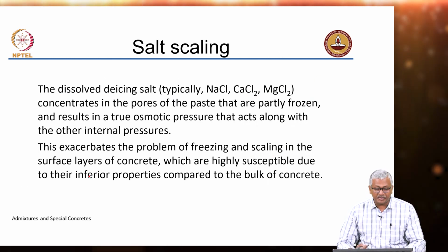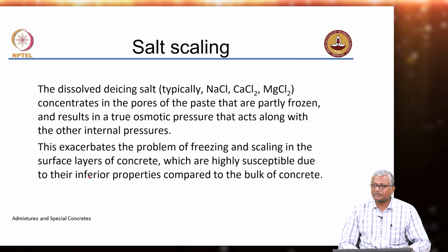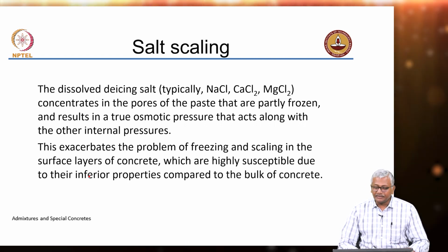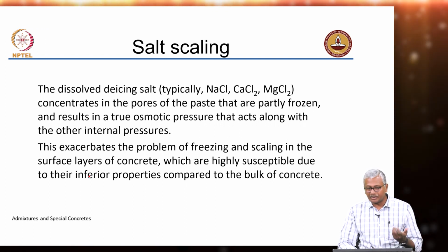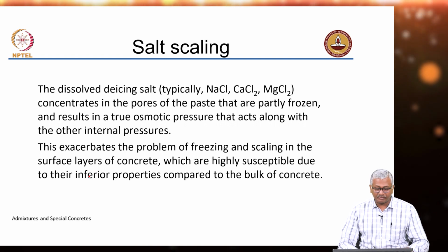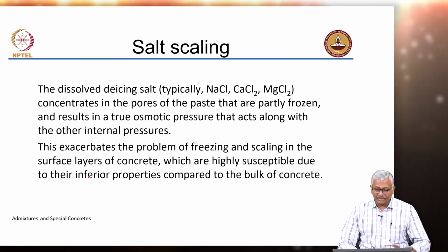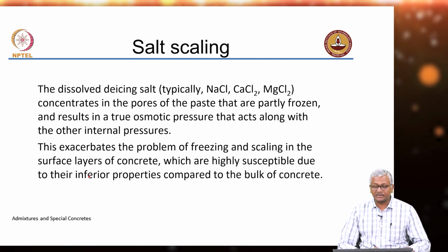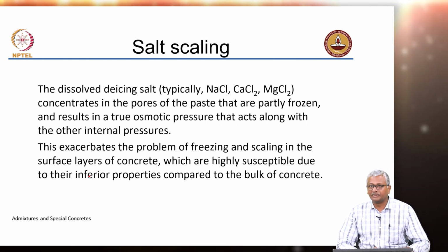So, that is the hydraulic pressure theory. In some instances, people also look at osmotic theory, but it is not as popular as the hydraulic pressure theory. Salt scaling, as I said, you put salt on the surfaces of concrete to prevent damage or to prevent the formation of ice, but these salts can start concentrating over time, and then you have an osmotic pressure that acts along with other internal crystallization pressures, and that leads to scaling of the surface.